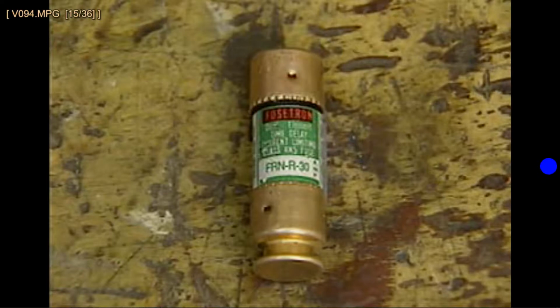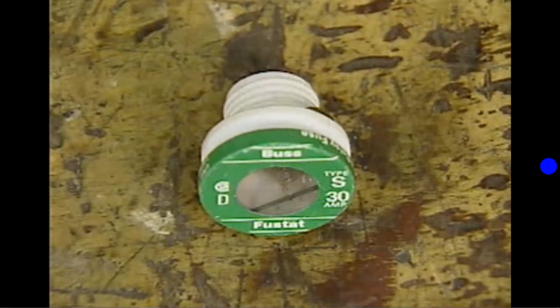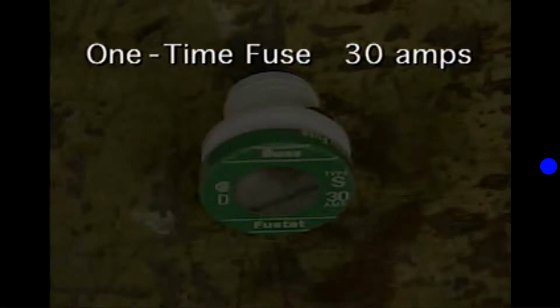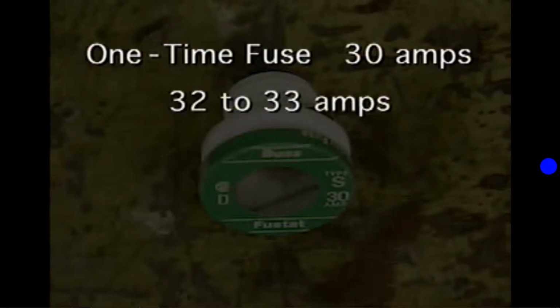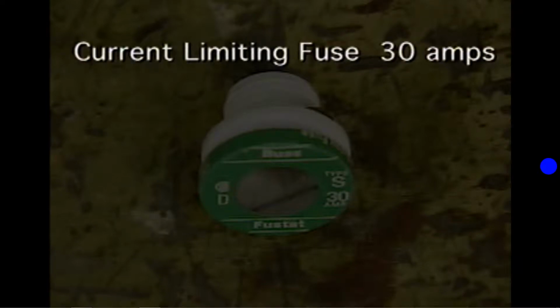The last type of fuse we'll look at is called a current-limiting fuse. A current-limiting fuse is a special type of one-time fuse that's designed to blow more quickly than a typical one-time fuse. For example, a one-time fuse with a current rating of 30 amps may allow 32 to 33 amps to flow through it for a short time before it blows. A current-limiting fuse with a current rating of 30 amps will blow more rapidly if the current exceeds 30 amps and will not allow a higher current to pass.